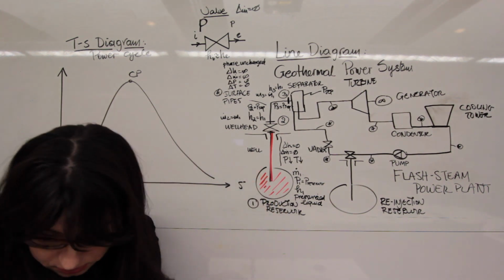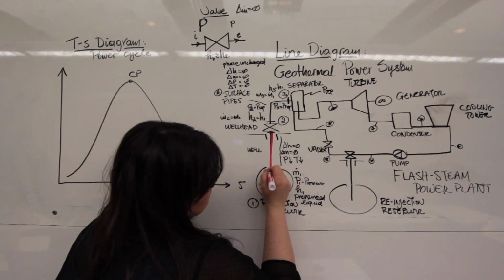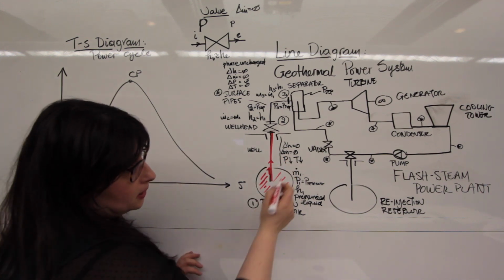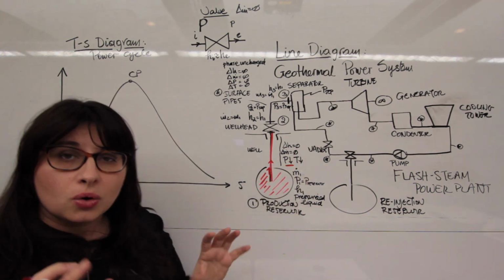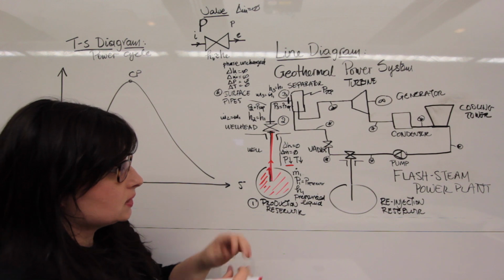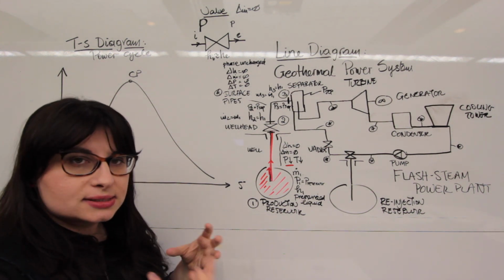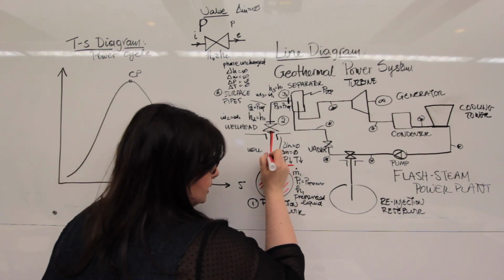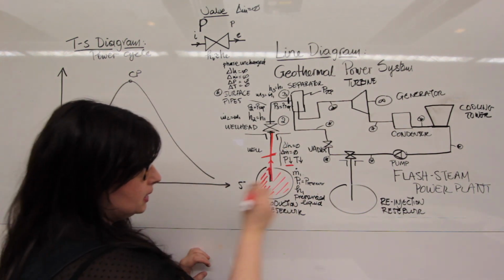I am flowing up the well. Right? I'm going up the well. What happens to my pressure? It's dropping. What actually happens is that it comes to a point where it drops and it can no longer sustain that pressurized liquid phase. That point, let's just assume that it's somewhere in here, right?